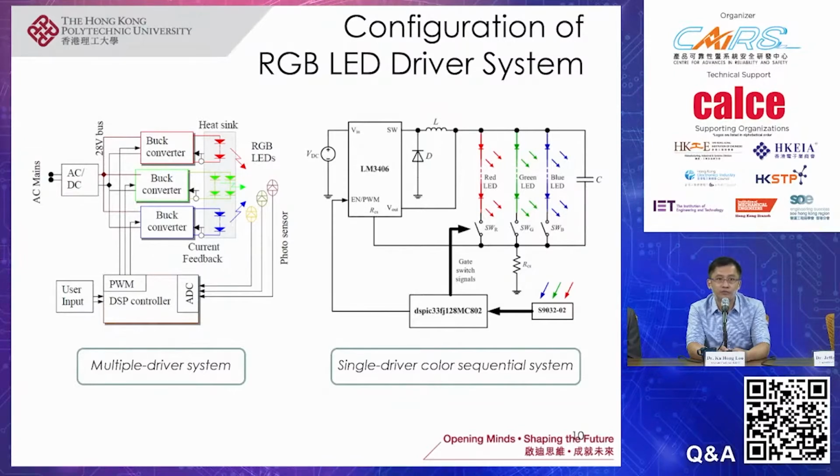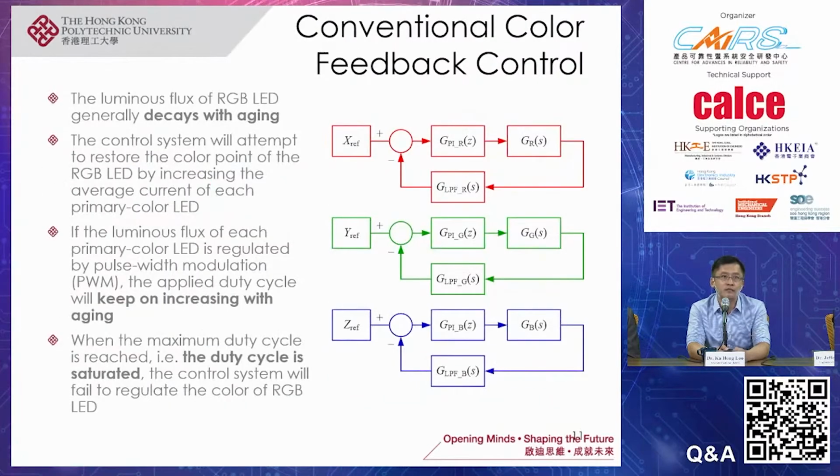Another option is that we can use one power supply to drive the three LEDs sequentially, which means that each LED will be driven one third of the time. So it depends on different considerations, cost or utilization of the LED. So we can have different options in terms of how to drive the LED. So let's come back to the control.